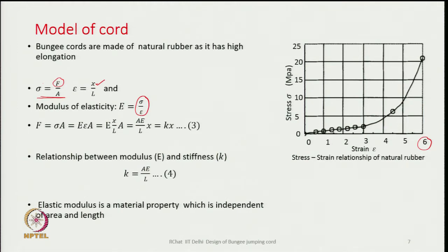From here we can write that force equals stress into area. If stress is modulus into strain, then force is modulus into strain into area, and strain we write as x by L. So, we are simply substituting them and arrive at this, that F is equal to k x, where k behaves